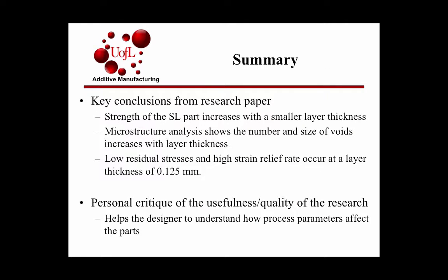So for a summary, the strength of the SL part increases with a smaller layer thickness. The microstructure analysis shows that the number and size of voids increases with layer thickness, and the low residual stresses and high strain relief rate occur at a layer thickness of 125 micrometers.